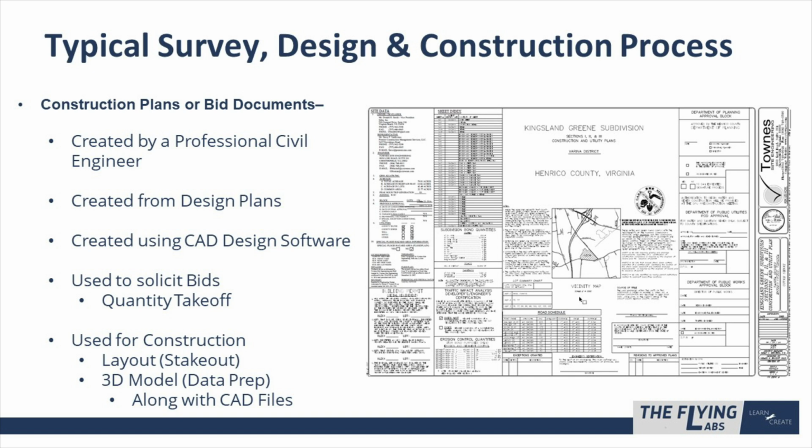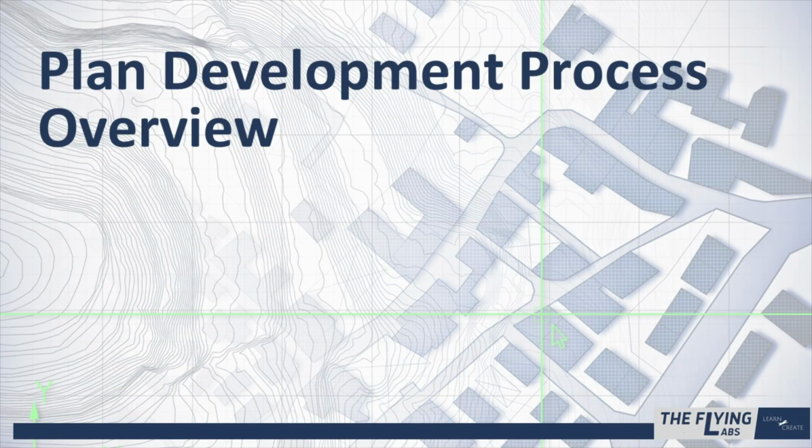Usually the data prep process happens after the contractor's been awarded the project. Most contractors will do a takeoff from these plans. If they win the project, then they will get the CAD data, and they will use these plans along with the CAD data to create a 3D model or any stakeout information that they would need to go lay out the project. So that's kind of the typical process of how plans are created and some of the higher level